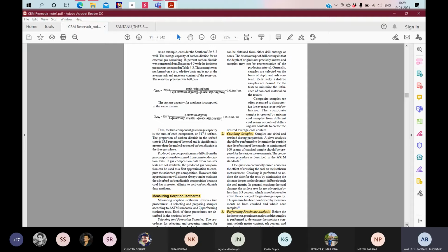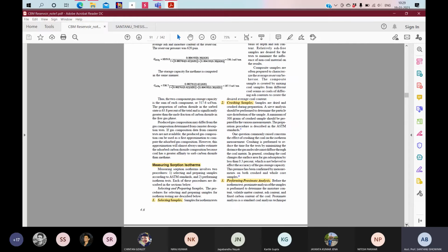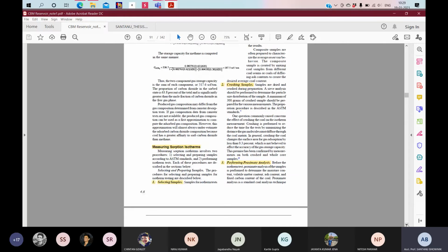Okay, so that if it is a dry sample, no further moisture can go into the sample. If it is a wet sample, no moisture should escape to the atmosphere. So that's why you have to put it in a separate sealed envelope and refrigerate it, because if it becomes very hot, then again the moisture will escape. Okay, so this is the concept. Please go through these steps and try to understand. I hope you will be able to understand this.